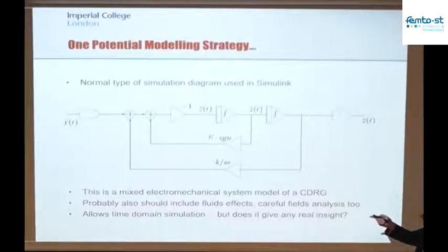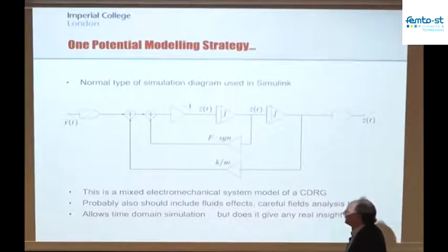But crucially, the damping force is now going to be determined by the voltage on the plates of the capacitor. And the voltage on the plates of the capacitor, of course, is a function of both the circuit design that we use and the way that we operate the circuit. We can try and set that to an ideal value. And then the question is, is the circuit good enough to allow us to set the conditions to the value that we choose? Or will it be somewhere close? How accurate will it be? Will there be a leakage current? All of these things we would need to start to explore to really understand the overall behavior of the system.